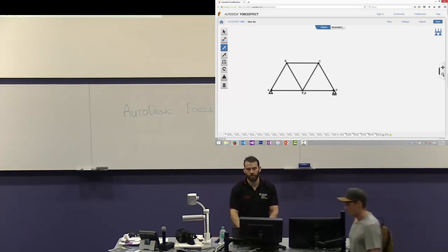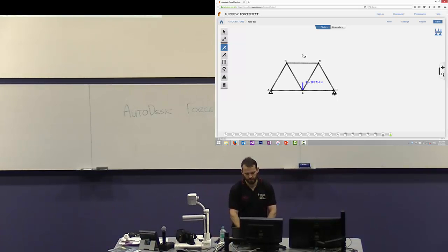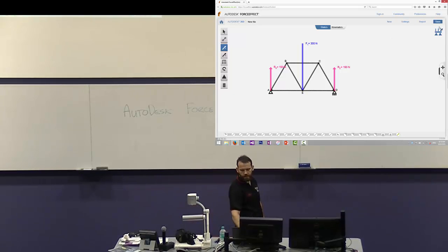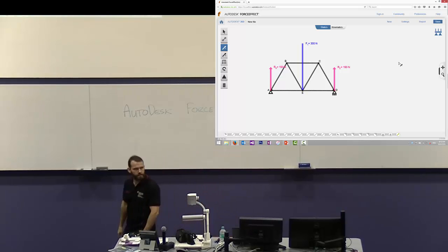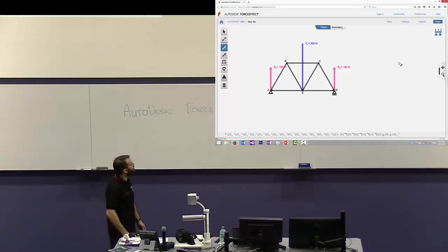We'll put it in the centre at the bottom, but if your bridge is designed such that you're carrying it at the top or whatever, you can do that too. Here we go, and I'll set 300 newtons. Once it's statically determinate, this little logo up here says you can solve. If that's red and off at an angle, it means it won't solve. But all of that's in the tutorial videos as well if you want to watch them and learn.